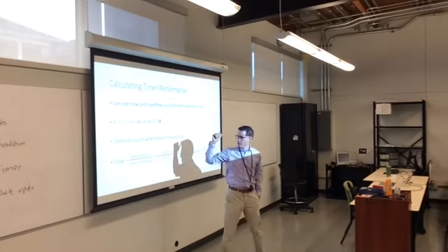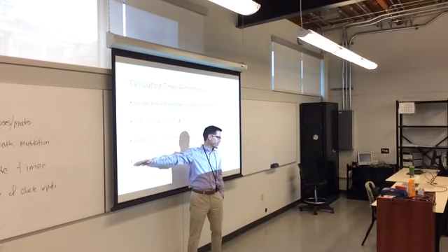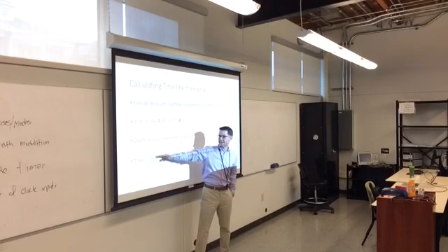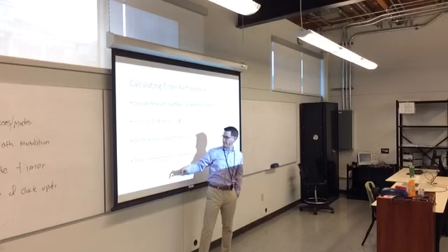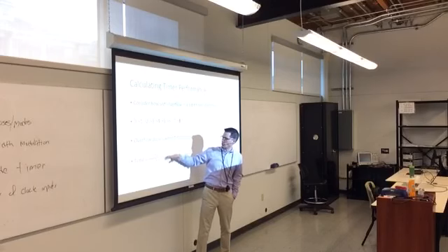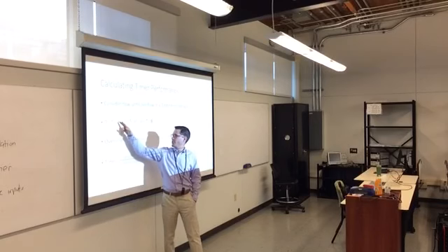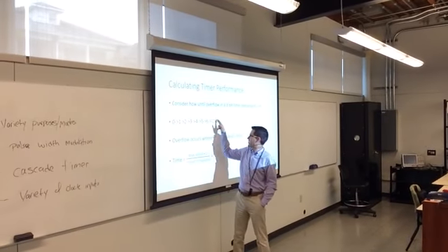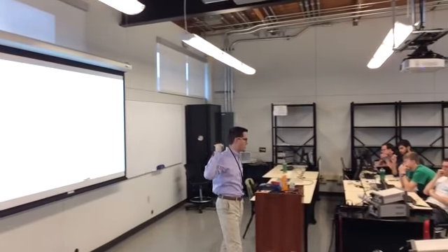So the amount of time that I can measure is equal to the maximum value I can hold plus 1, so it's 2 to the n bits, divided by how fast I'm counting. So I can go 1, 2, 3, 4, 5, 6, 7, 8. And I'm doing that at 1 hertz. That means I can measure out about 8 seconds with this counter.